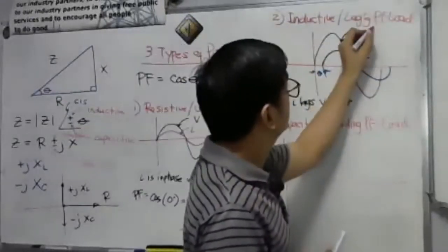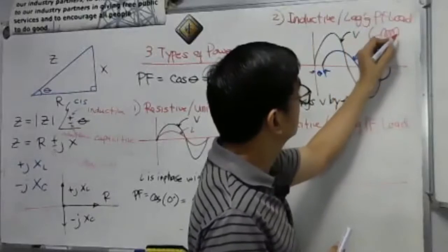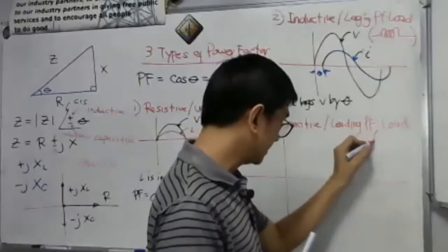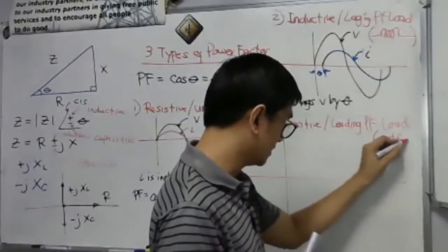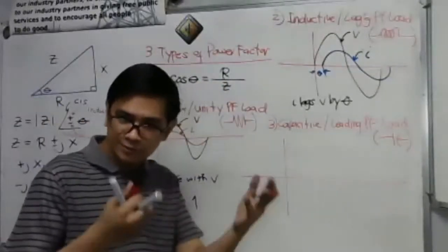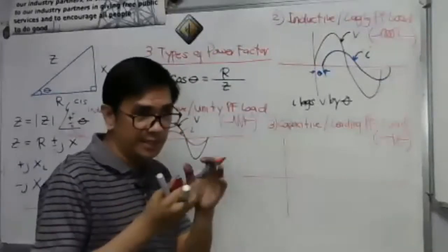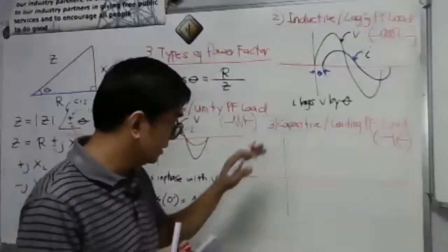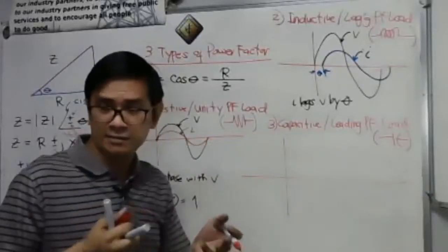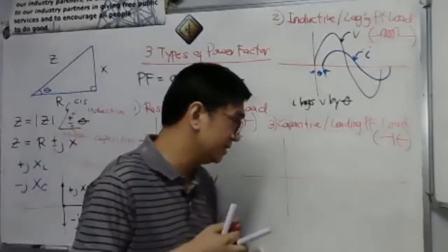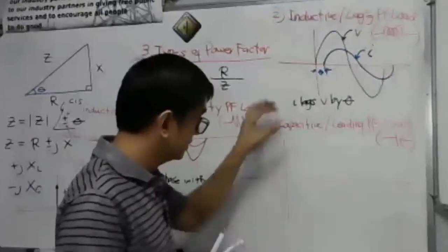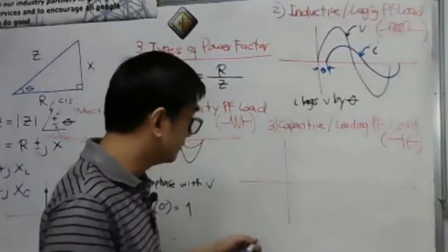You have inductive load, you have high inductance, you have an inductor. Of course, for leading or capacitive load, there is a presence of a capacitor. Let's say for a synchronous motor, or synchronous condenser, or let's say there is a building with capacitor banks, there's a tendency that it will become leading, that it will have a leading power factor. That's a possibility. That is overcompensation. Anyway, we have a discussion about power factor correction. We have a separate subject for that.